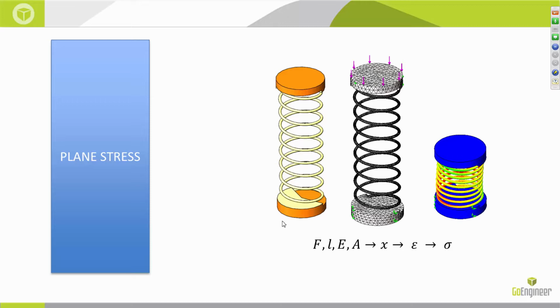So you start off with the forces and the boundary conditions. Utilizing these boundary conditions, the displacement field is figured out through stiffness matrices. And using the displacement field, there are relationships between how each node in your finite element model displaces and what is the associated strain with those displacements. Now, after the strain is figured out, well, stress is proportional to strain. Maintaining that proportionality, the stress distribution is figured out. So this is essentially the process, and the equations that govern this process are called constitutive equations.